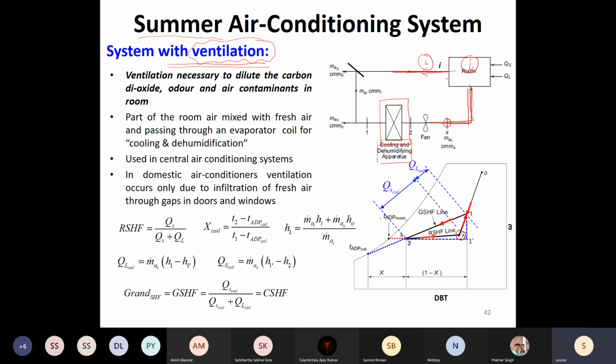Okay, so just because there is a duct doesn't mean that it will supply cold air. So we require two sets of ducting. So ducting is not shown completely over here. So this is the return air. Through a valve, we exhaust some of the air to the outdoor, and the rest is recirculated. Okay, so this is like a valve. We will see how this valve looks like.